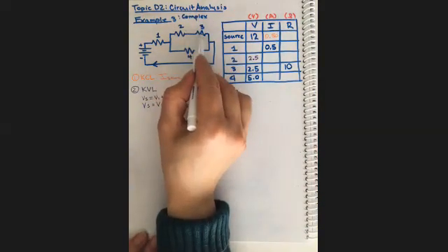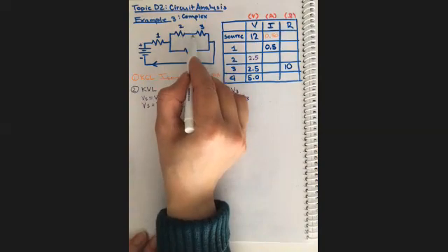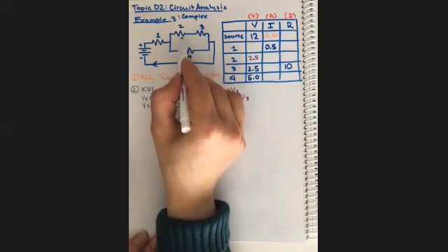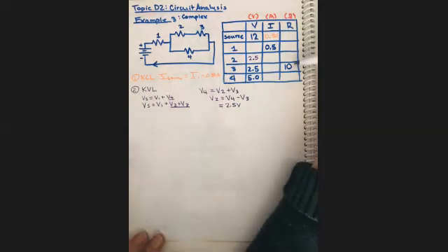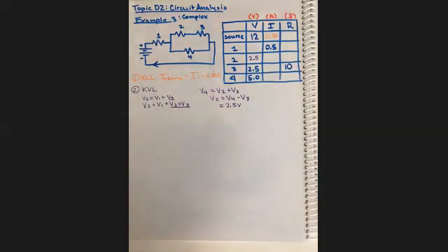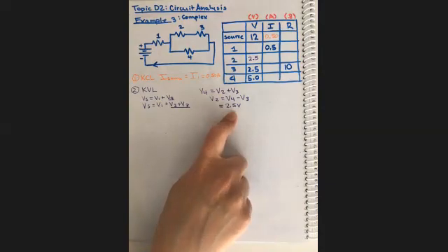The voltage drop does not have to be the same. It's a coincidence, or we'll see later, it's because the resistors are the same. So remember, the voltage drop is like how much energy is lost across it. So if current is the same, a certain constant resistance from one to the other is going to result in a constant energy drop from one to the other.